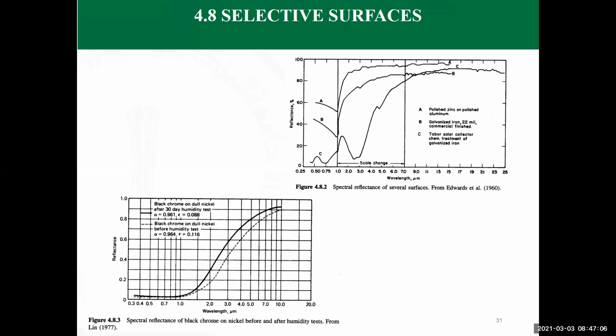So the values here are showing low values of reflectivity at a certain wavelength, and the distinction is not really a straight line, but it is gradually increasing to a high value for high values of the wavelength, the long wavelength radiation, which is corresponding to relatively smaller temperature of the surface. Smaller temperature, I'm talking about the order of 100 to 500 or so.